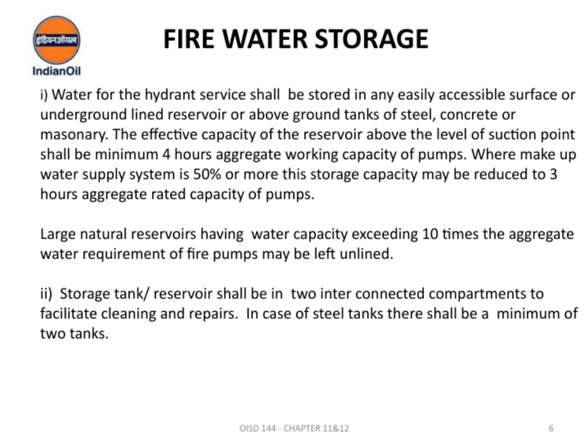Now, if the make-up water supply system provides 50% or more of the total water, this storage capacity can be reduced to 3 hours of the pump's rated capacity. It's also interesting to note that large natural reservoirs, which have a water capacity exceeding 10 times the total water requirement of the fire pumps, may be left unlined. This helps in saving costs and makes use of natural formations when feasible.